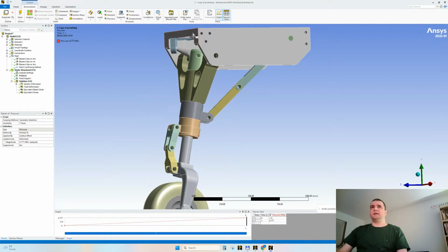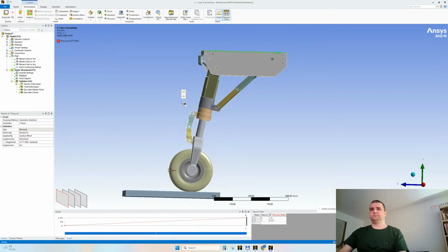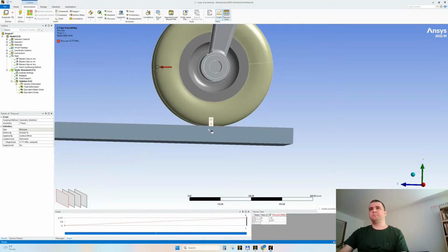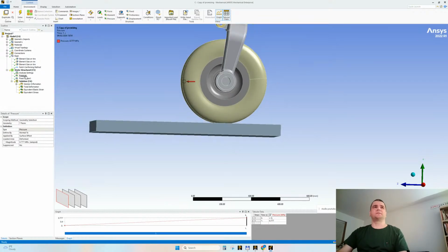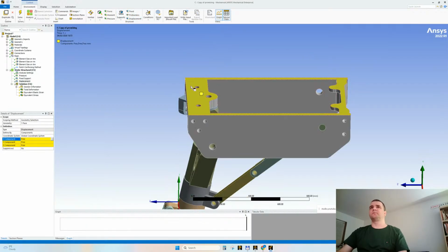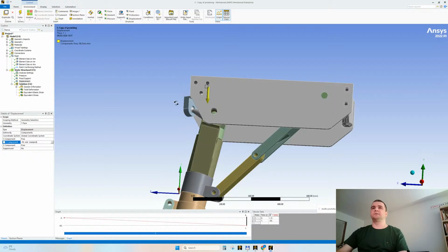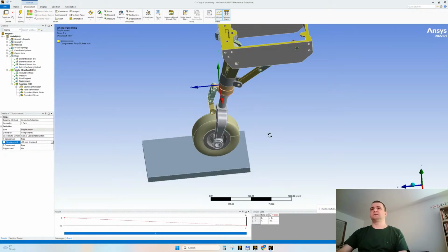Let's keep it like this. And I will press this, yes, I will displace it downwards with maybe something like 70 millimeters. Yeah, 50 millimeters, I wanted to say 50 millimeters. So displacement, this thing, yes, 50 millimeters. Downwards means minus 50 millimeters on the y-axis. Perfect. Let's have it like this.